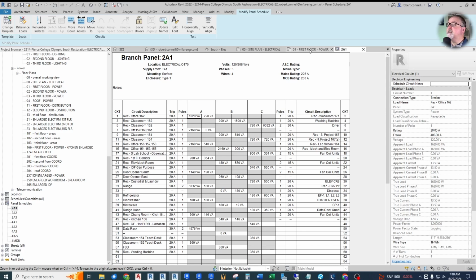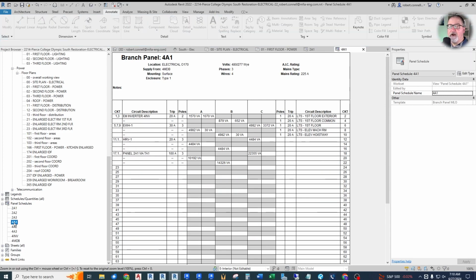But my point is that if I were to go in and change, like I did those lights, if I change the lights to a different wattage, it adds them up. So let me go to the 480 volt 277 panel. And as you can see here, lights, it's added up all the lights, 1070, 852. It's down to the VA. And as I changed those lights from 30 to 40, it bumped up the connected load, all behind the scenes.